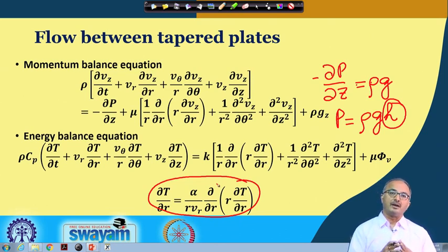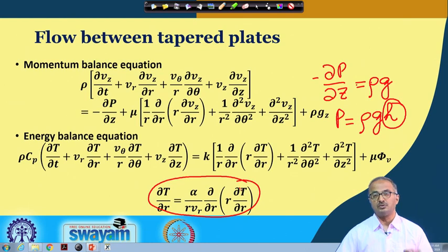So, that is how you find that the whole problem becomes a bigger problem, even though the concern is only for the temperature. If you can assume these velocities to be constant, with no gradient, then we need not solve the momentum balance, we can just go directly to the energy balance equation.